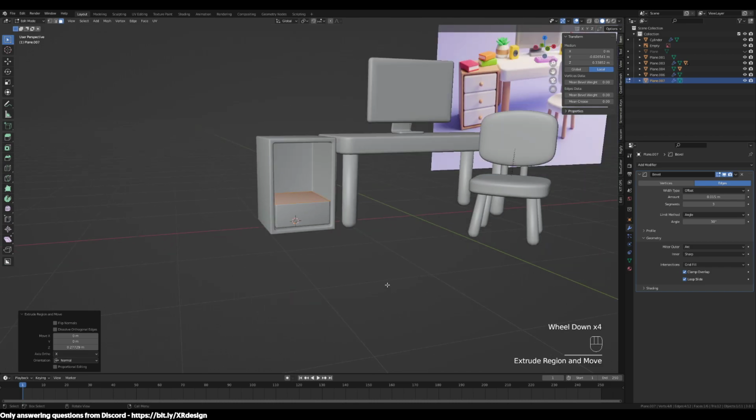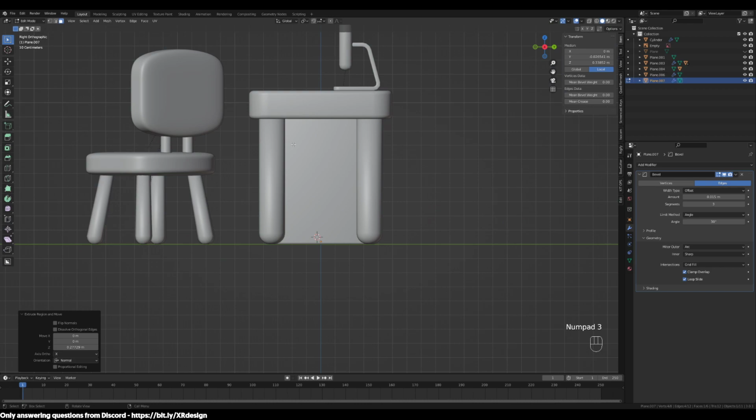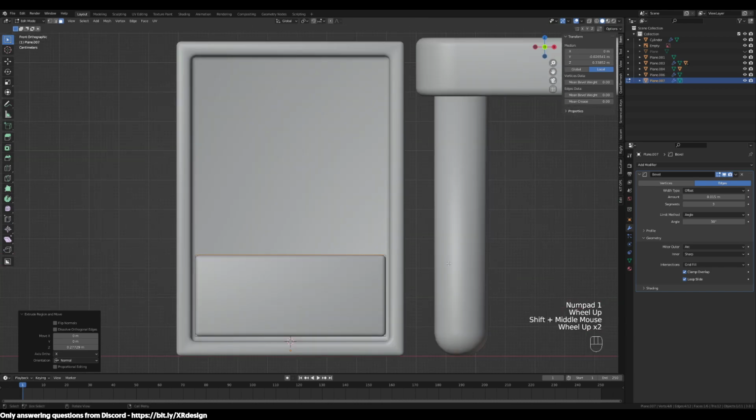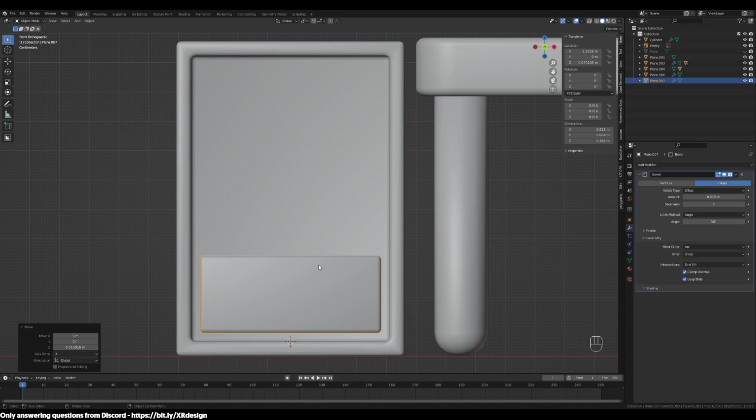And when you do, you want to make sure you have room for the other two. So I'm just going to go to front view and make sure I have enough room. In this case, it's better to have enough room than trying to overextend and not have enough, because we can tweak the space between the drawers to make sure that everything fits.